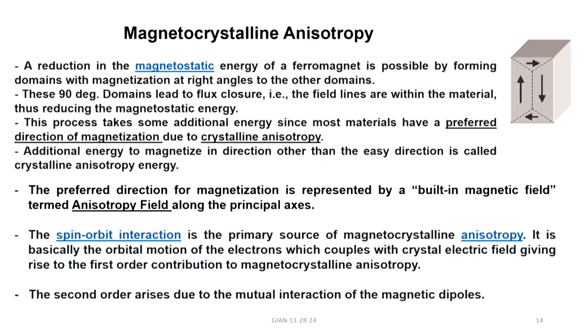Barium and strontium ferrites are uniaxial, the field is along the C direction, but some of the hexagonal ferrites have an easy plane. So it does not matter, this is the C plane of the sample, and any direction within the plane is an easy direction. Okay? So, there is no preference. There are easy direction and easy plane anisotropies, and that is the source of magnetocrystalline anisotropy.